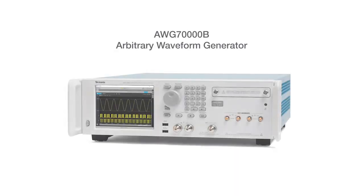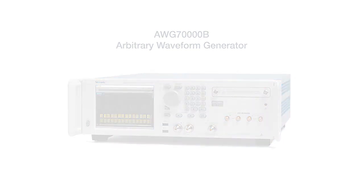You can either run the software on the Windows operating system of the oscilloscope or on a separate PC. Remote desktop applications can be used to remotely access the scope operating system. For automated testing, SCPI remote interfaces are available to accelerate the transition from the design process to manufacturing. The Tektronix AWG 70000 provides low noise, flexible generation of multi-channel wideband signals complying with the 5G NR standard.